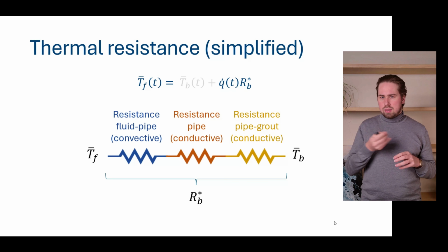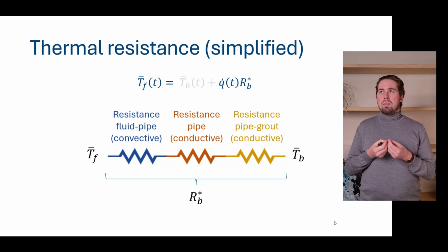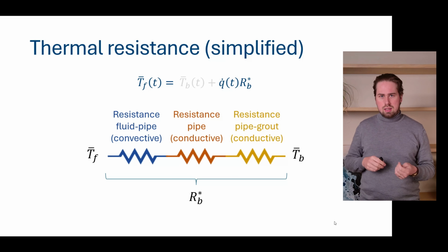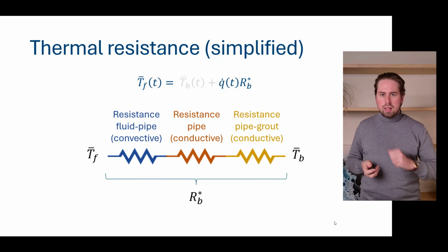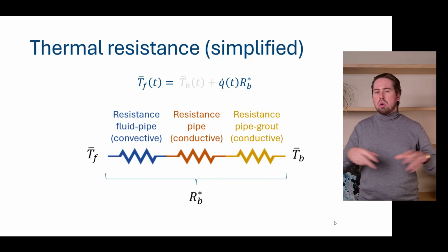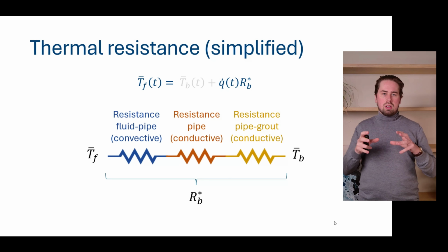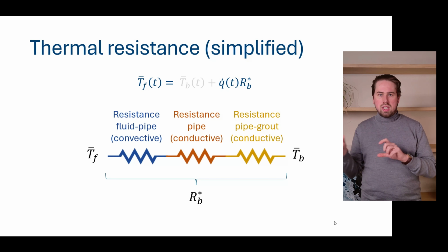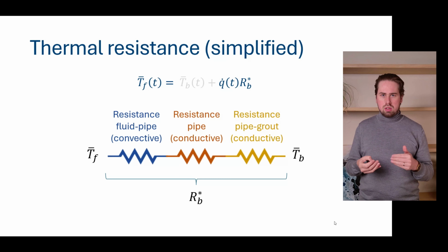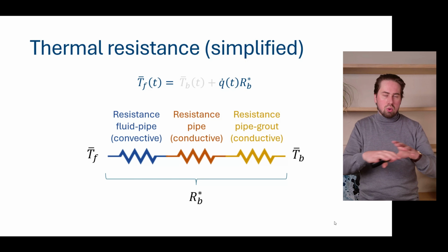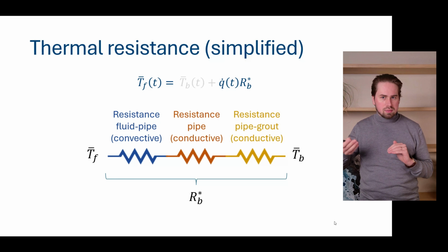So if we then take a second look at our equation, at this very instance, we have a certain borehole wall temperature. If we are now extracting 10 kilowatts from the ground, our borehole wall temperature will not change in the matter of hours. So that's why we can differentiate between short and long term. When we're just talking about powers, we can assume that the borehole wall temperature is constant and that it's just the fluid temperature that varies.